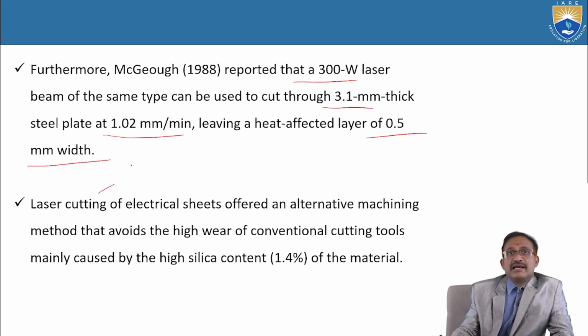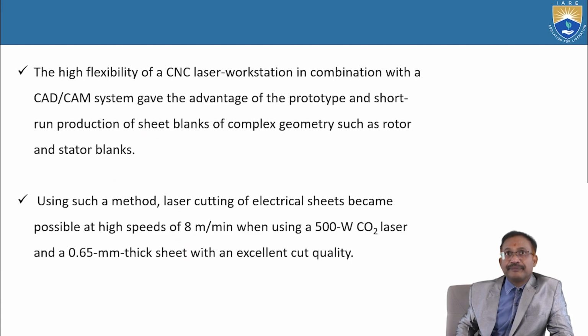Laser cutting of electrical sheets offered an alternative machining method that avoids the high wear of conventional cutting tools, mainly caused by the high silica content, that is 1.4 percent of the material. So this is regarding electrical sheets, which are offering an alternative machining method that avoids the high wear of conventional cutting tools.